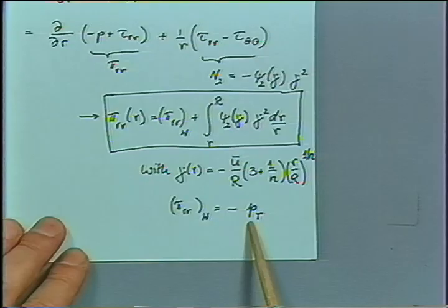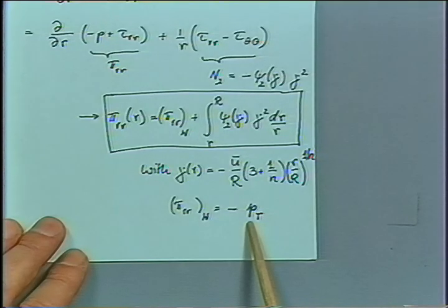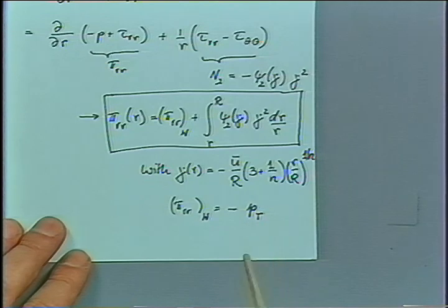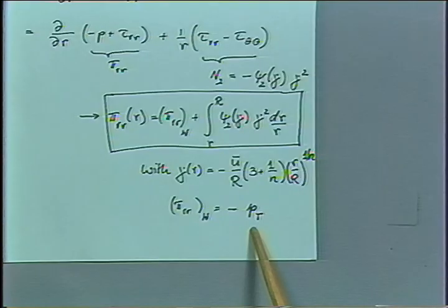That's an example where you obtain the absolute value of the normal stresses by introducing the normal stress at the wall. So that's where you get your absolute values. That's an important point in the modeling, since otherwise in constitutive equations we always deal with normal stress differences between the first and the second direction and the second and the third direction. So this is where the absolute value comes in.